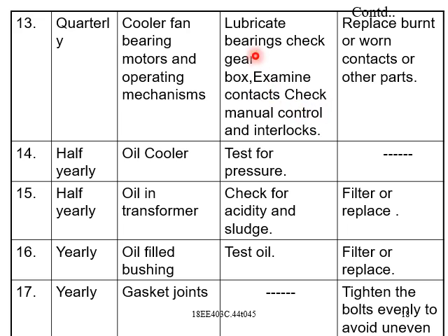The inspection to be done is: lubricate bearings, check gearbox, examine contacts, and check manual control and interlocks.